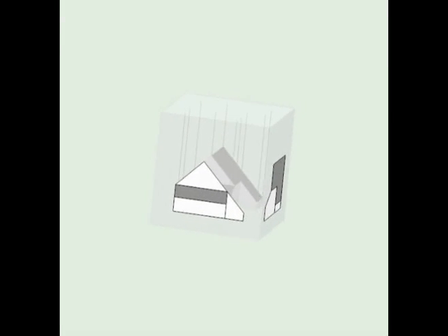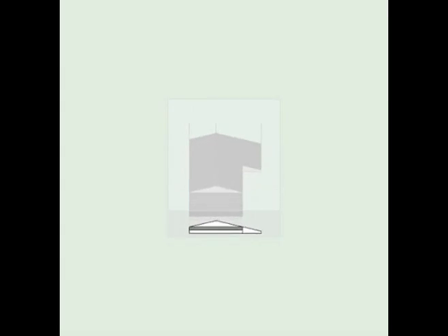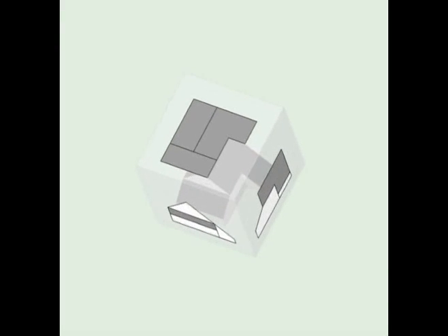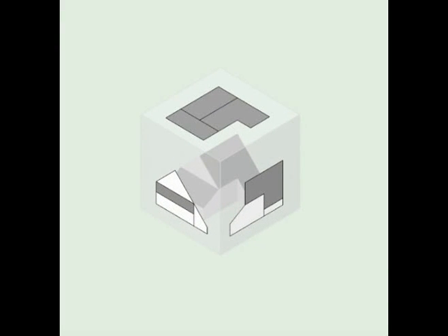Onto this picture plane, we construct another orthographic projection. Rotating this construction again shows the perpendicular relationship of the projectors to the picture plane. This third orthographic projection gives us information about the object which was missing from the first two projections. This pictorial view illustrates the relationship of each orthographic projection. The three picture planes which are perpendicular to each other form a transparent box around the object.